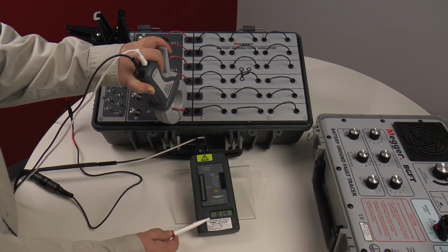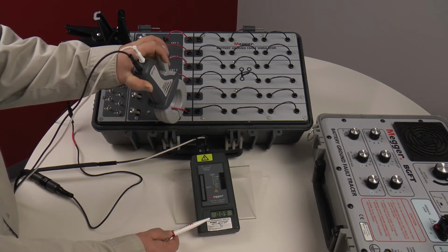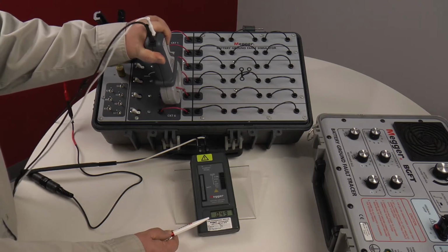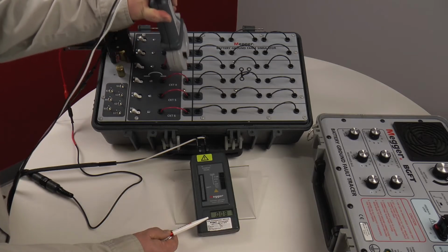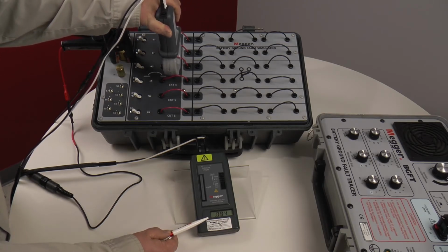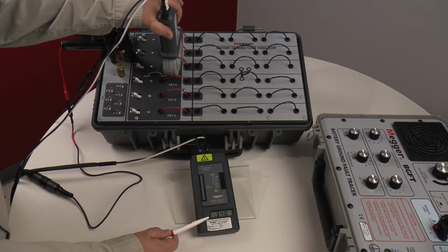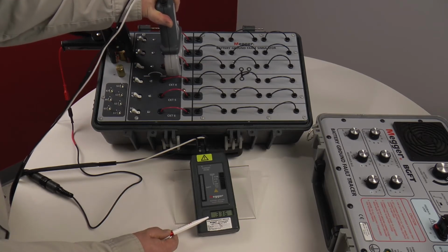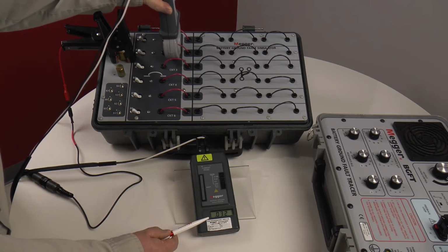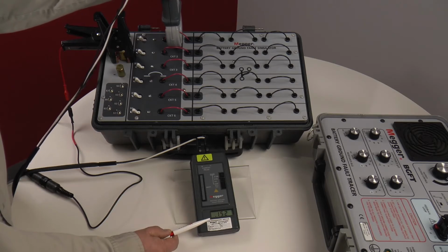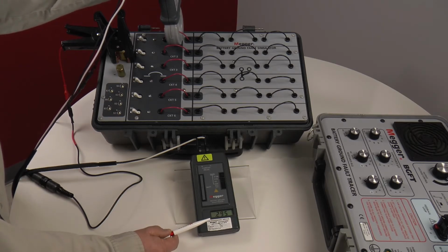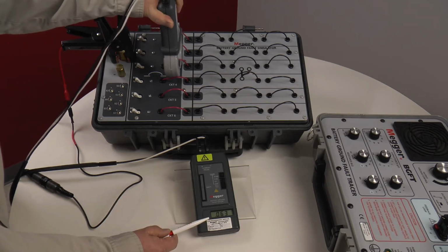Checking circuit 6, we see there is no fault current, so we go to circuit 5, and again, there is no fault current. So we go to circuit 4, and there is no fault current here either, so we go to circuit 3. Notice we have some of the fault current on circuit 3. Now we continue on to circuit 2, and we see there is no fault current on circuit 2. So we proceed to circuit 1, and here is the rest of the fault current. So we know we have fault current on circuits 1 and 3.